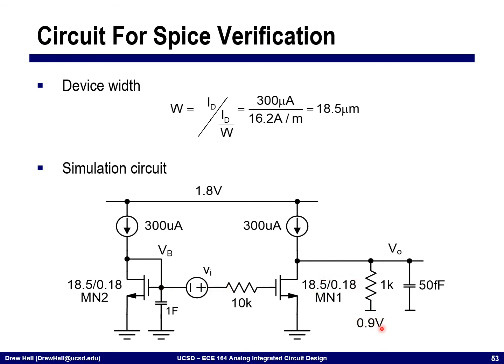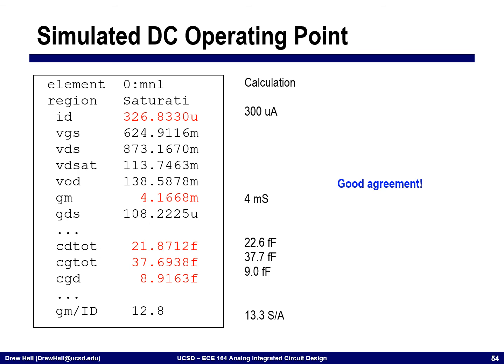Over here, I've replaced this with 0.9 volts, and everything else is exactly from the specs that we got, driving a 1 kilo ohm and a 50 femtofarad load. Okay? So let's simulate this. Looking at the operating point first,